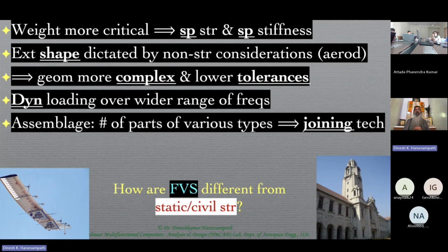integrally. In other words, you're essentially manufacturing almost an entire wing, for example, or a very large section of the wing, as an integral structure. You don't need to use rivets or bolts in order to join them. At the most, you might use adhesive joints. And in some cases, depending upon the certification requirements for larger and larger aircraft, you might have requirements for bolts, but not as many as there were in the metallic structures.